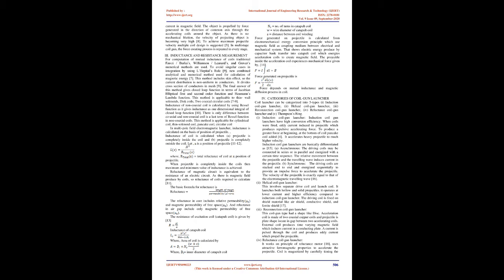Inductance of non-coaxial coils is calculated by using Bessel functions, as this gives inductance as a one-dimensional integral of a closed-form function. The only difference between coaxial and non-coaxial coils is the last term of the Bessel function in non-coaxial coils. This method is applicable for cylindrical coil, thin solenoid coil, pancake coil, circular coil. In multipole field electromagnetic launchers, inductance is calculated on the basis of the position of the projectile.